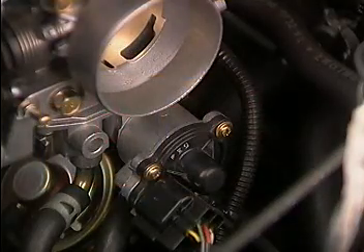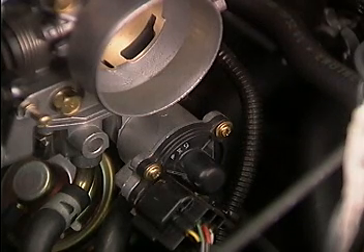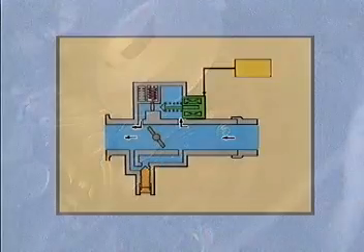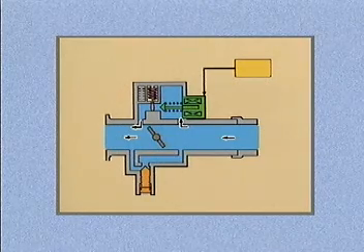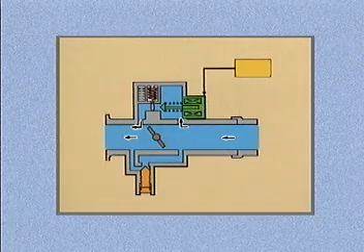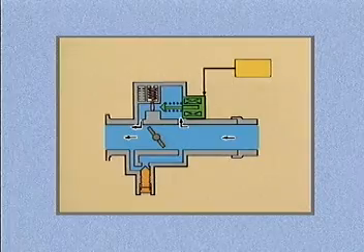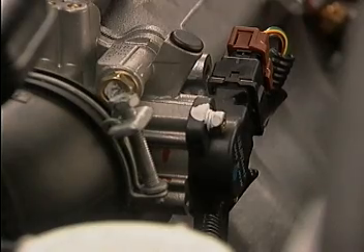The new idle speed control system used on the 1.5 liter and the 1.8 liter engines is the flow-limited control system used on Monteros with 3.5 liter engines. The dedicated wax pellet type fast idle air valve has been eliminated. A stepper motor controlled idle air passage is used for all closed throttle idle air control. A bimetallic flow limiter is used to control the maximum airflow allowed at idle as engine temperature changes. A new throttle position sensor with a built-in closed throttle position switch is smaller, lighter, and more resistant to engine